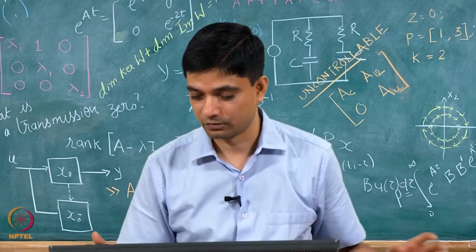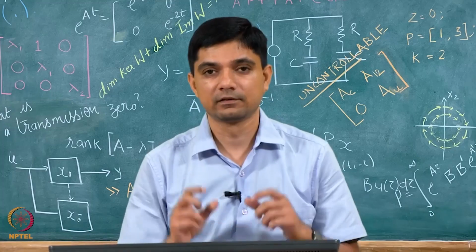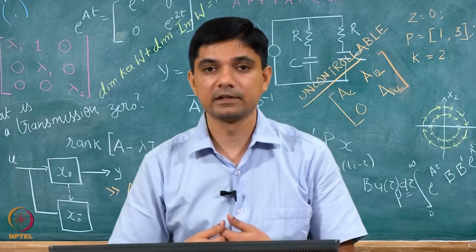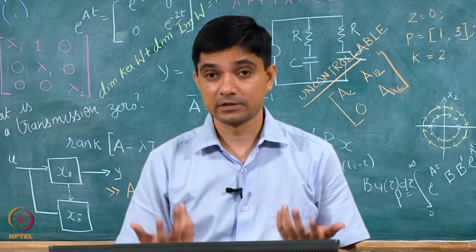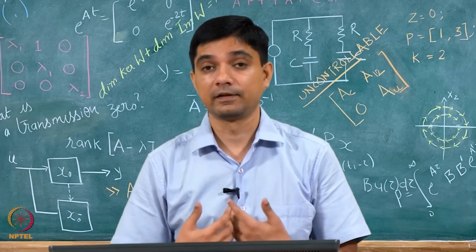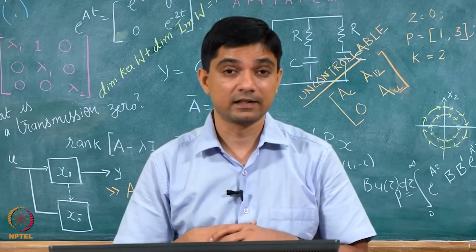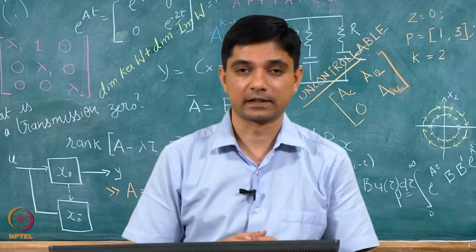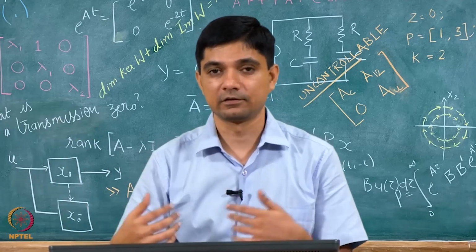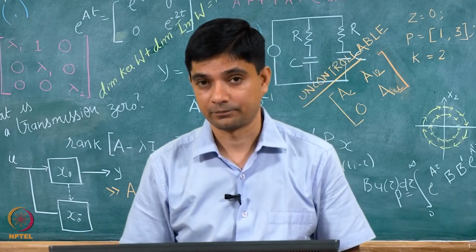So, it will be some 0.4 or things like that. We can just play around with the quantum of delay and check whether or not the system is stable. So, what is the observation here? Even though there are some systems which are stable independent of delay, some systems are stable depending on the delay. For some small values of delay, say in this case 0.4 seconds, it is acceptable, but for larger values my system goes to the verge of instability. So, this is a little better result than what we had previously, right.